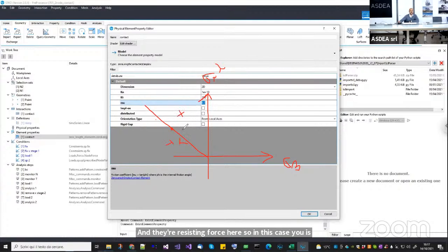If you are outside, you are in slip condition, so you move over the yield surface. And any point here, the maximum shear force that separates the stick condition from the slip condition, is given by minus sigma n times mu. Minus, because only if you are in compression. If you are in tension, of course, you don't have any friction force.